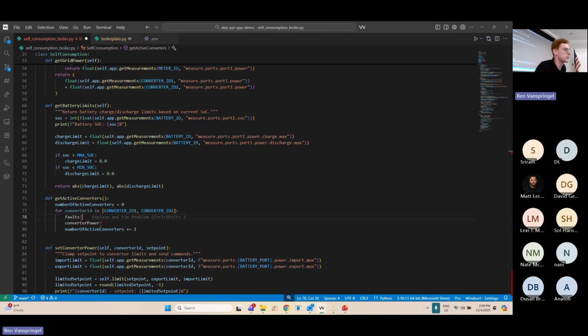We gain a lot of experience by having our own DC lab out here, and having the equipment up and running in a test environment where you can go over these scenarios one by one and get familiar with the devices that you have. That is from experience. You have to know a converter, you have to know a battery, its operating sequence. So it's testing in a controlled lab environment.